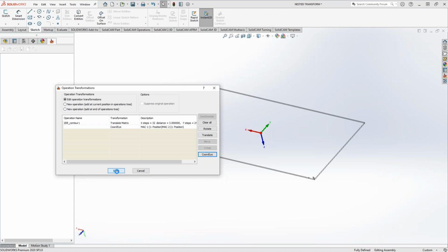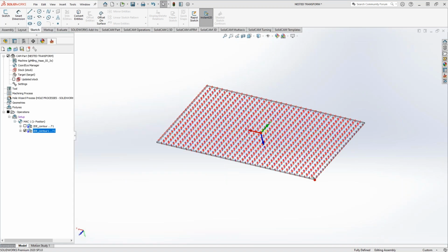And because it's a tombstone, it's rotating, you want to minimize tool changes. You can use that option in the top left corner so that you actually shuffle the toolpath. So you actually get part 1, face 1, part 1, face 2, part 1, face 3, and it's all the same tool. So once you get the toolpath on screen, shuffling it, organizing it, sorting it, that's all up to you, but you can do as much sorting as you need to minimize tool changes, minimize cycle time, whatever it is you're looking to do.